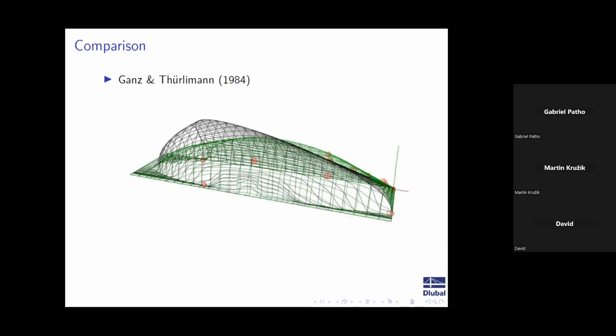These are my normal stress axes, and in the other direction is the shear. That would mean you would need to apply very high shear, so you would need some test data from some earthquakes, basically. So that's why all the test data are around the perimeter. What happens inside in the top, nobody really wants to know, I guess.